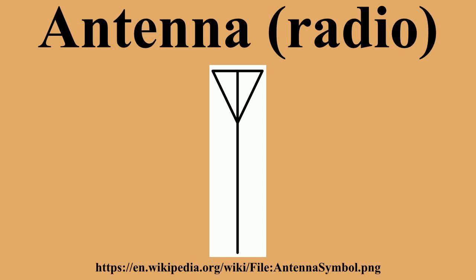Reciprocity. It is a fundamental property of antennas that the electrical characteristics of an antenna described in the next section, such as gain, radiation pattern, impedance, bandwidth, resonant frequency and polarization, are the same whether the antenna is transmitting or receiving. For example, the receiving pattern of an antenna when used for reception is identical to the radiation pattern of the antenna when it is driven and functions as a radiator. This is a consequence of the reciprocity theorem of electromagnetics.